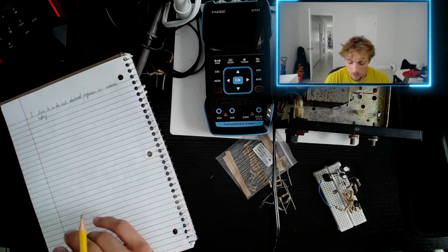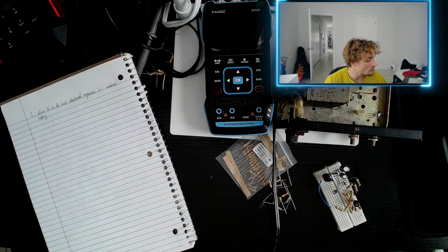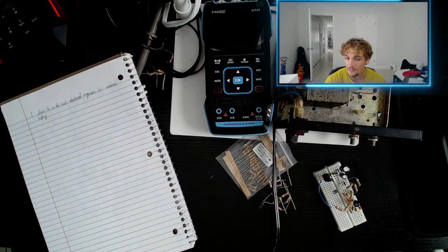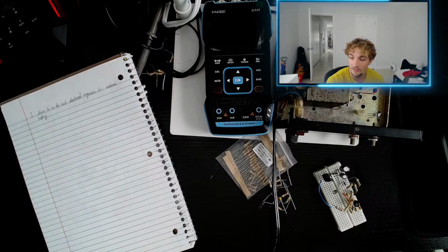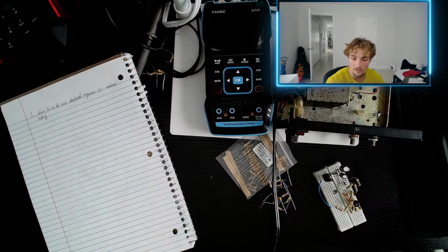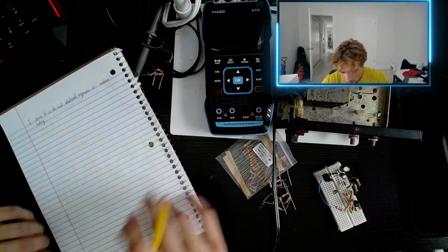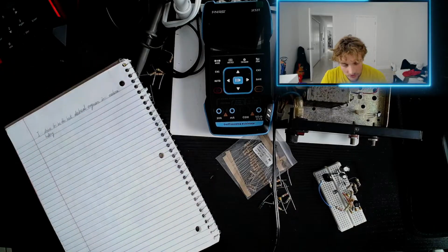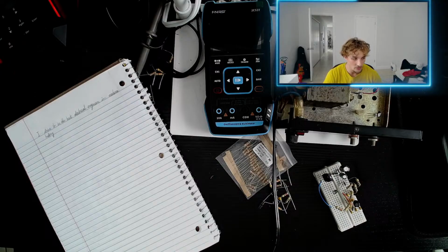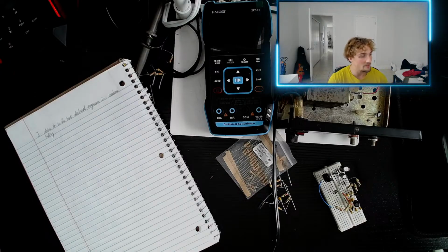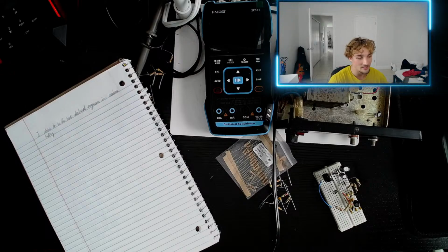Fair. Okay. Alright, so I'm going to jump into the Colpitts oscillator. They have very different, very distinct topologies, but we're going to look at this particular one where we tap the feedback in between the series inductor and capacitor. And then we have our second capacitor in parallel with those two. So I'm going to draw it out. First, we're going to start with a bias point operation of our 2N3904 NPN BJT, bipolar junction transistor. We're going to begin with this, and we have to set the operation point.